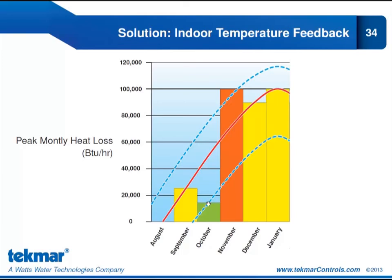Now if I go into the month of November, I can see I'm experiencing a higher heat loss than the reset curve had predicted. So I need a higher supply water temperature to make up for the increased loss. Indoor temperature feedback will shift the heat curve up so that I have higher supply temperatures than what was originally calculated.